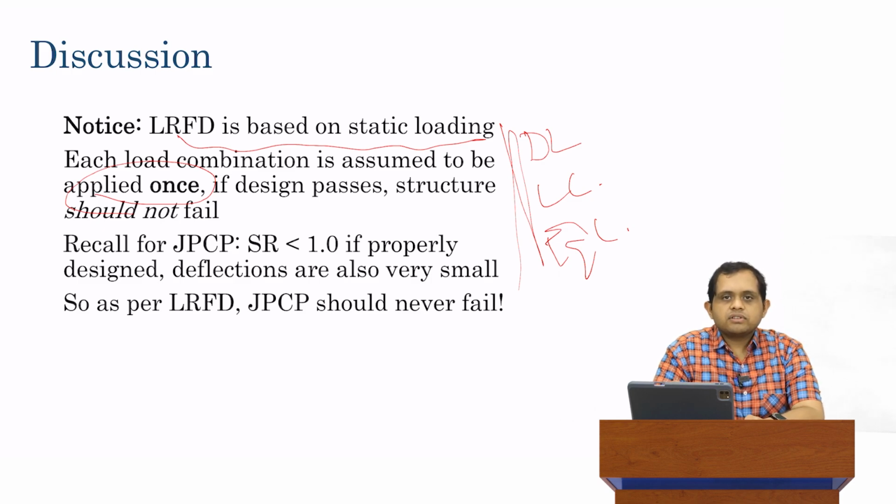Under these conditions, if in service we find that the loads are within the limits that we've prescribed, that is, if the in-service loads are actually less than the factored loads, and if the design was done correctly, and obviously if it was constructed correctly, then the structure should not fail. The structure should never fail as long as the loads are less than the loads for which the design was performed. That is a basic assumption of LRFD design.